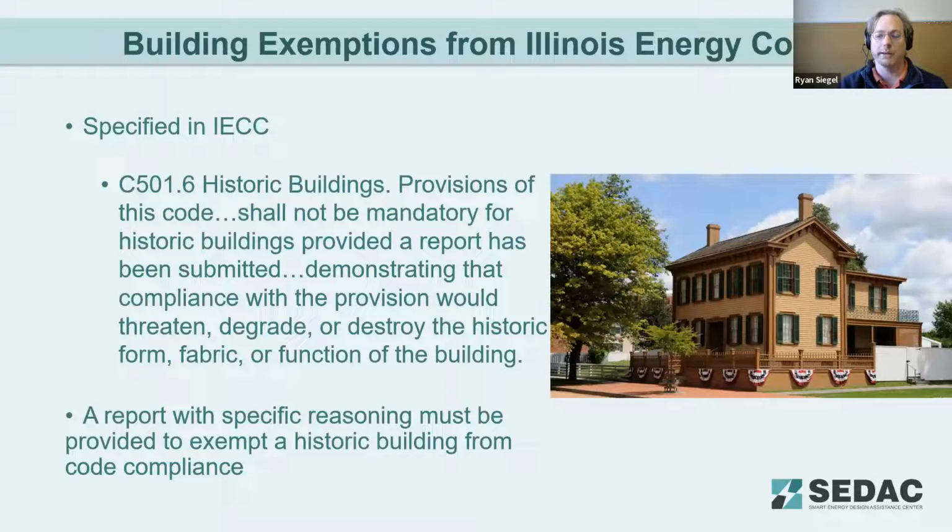we didn't want to necessarily. Here we're looking at a very nice historic building, and trying to bring those windows up to the current fenestration U-factors might be extremely difficult or very problematic, but you may be able to improve the current windows to the best of their functional ability.